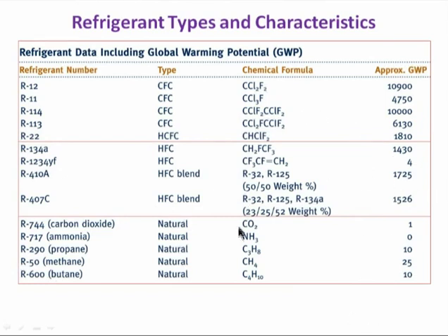So these are the different refrigerants. Ammonia also has good thermodynamic properties, but it is very toxic, and leakage of ammonia causes a harmful effect. So these are the advantages and disadvantages, and we have to optimize and look at the application, particularly for which application we are going to use the refrigerant. Accordingly, refrigerants are selected for the refrigeration system as a working medium. So we have talked about the different types of refrigerant used as a working medium for the refrigeration system.